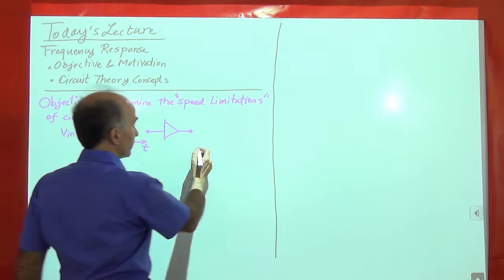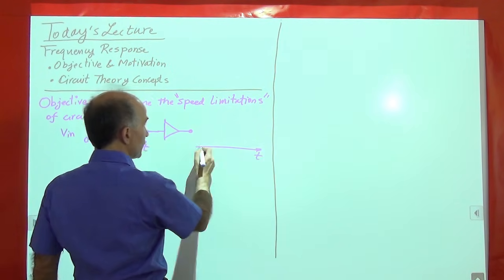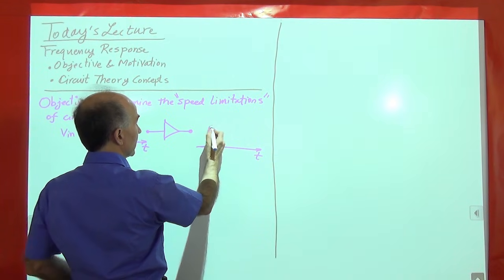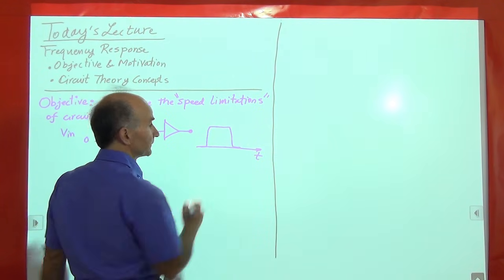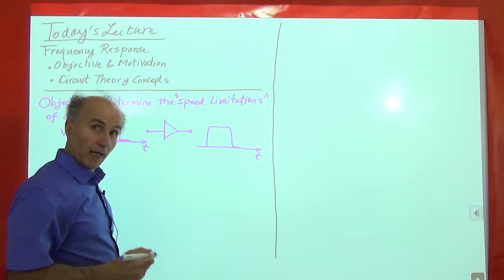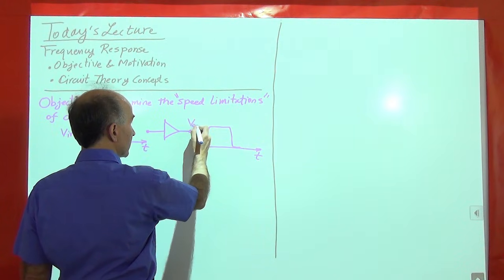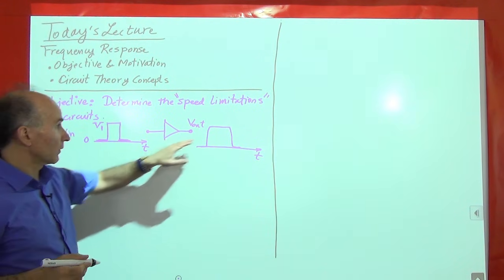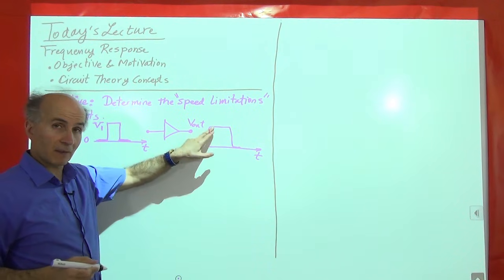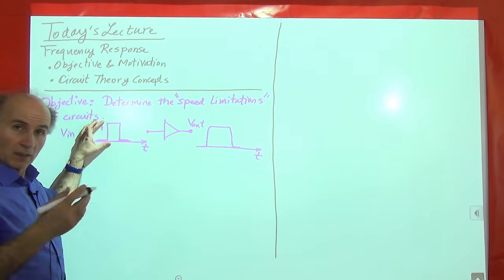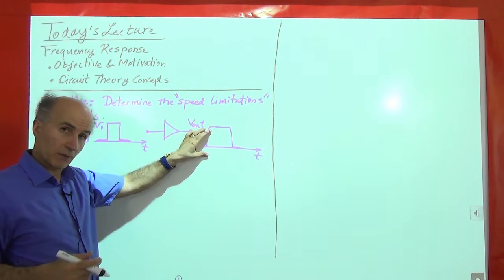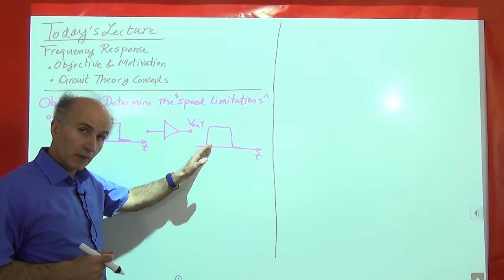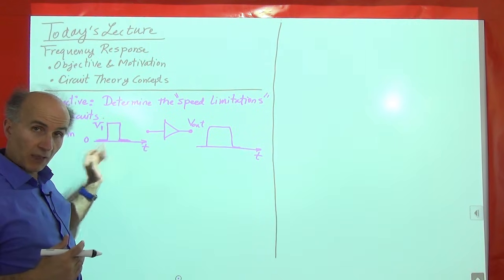Well, if the output of the amplifier follows the input pretty well, so it jumps up pretty well, and then jumps down pretty well, then that's a good amplifier, right? So V out has this type of characteristic. Now, it may start from 0 or some amount, and then it goes up to this value. Maybe we have amplified the signal. So if this change is, let's say, 100 millivolts, this change might be 200 millivolts. Okay? All right, so that's a pretty good amplifier because the output responds quickly to the input changes.